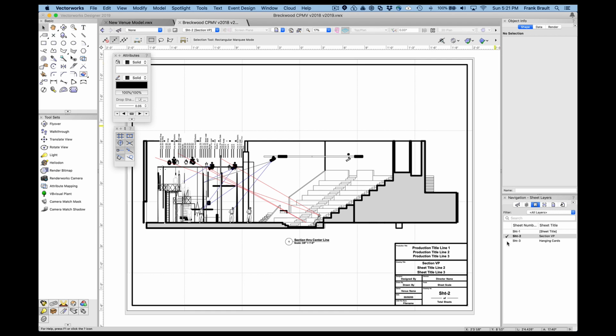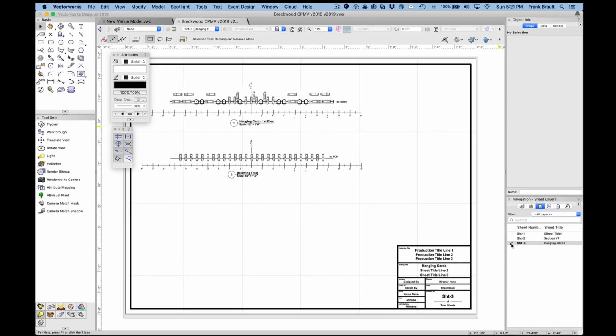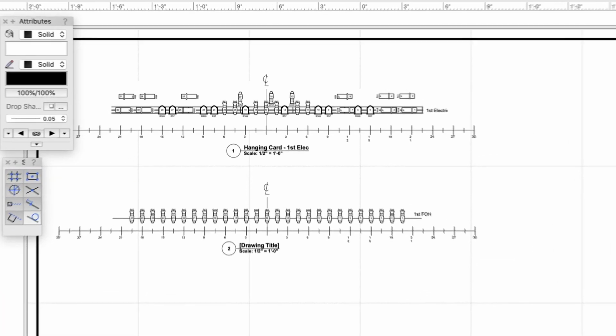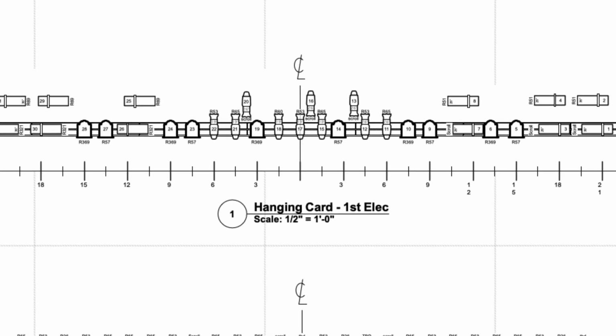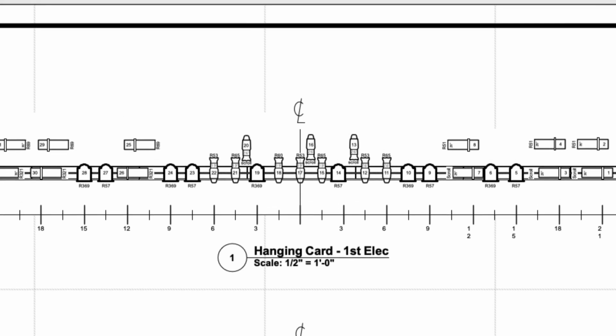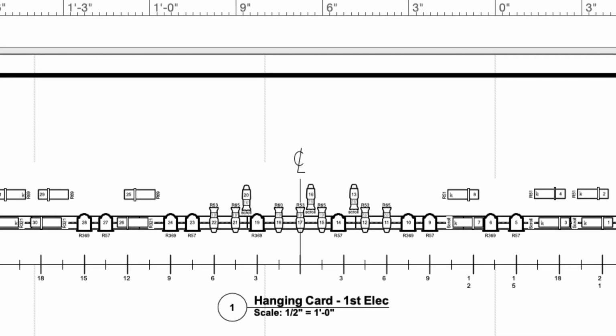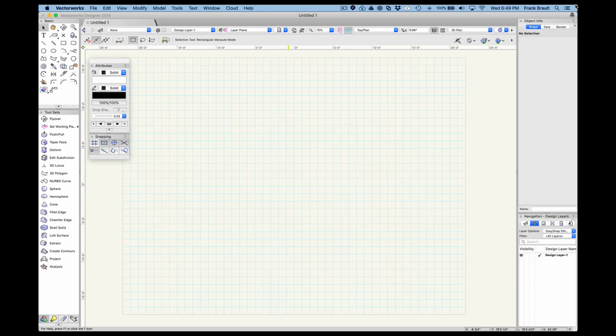These views are essentially filters of the model, showing specific data sets from the model in a traditional projection with annotations which explicitly denote information such as dimensions and other notes that are implied but not otherwise called out in the model. Viewports are the way to present a model in this way in both 2D and 3D projections, and the way to calculate the project documentation along with quantities all in one place. When you do lists in Excel, they're separate from the drawings, making it necessary to duplicate parts of the model in multiple places, and this is not ideal.